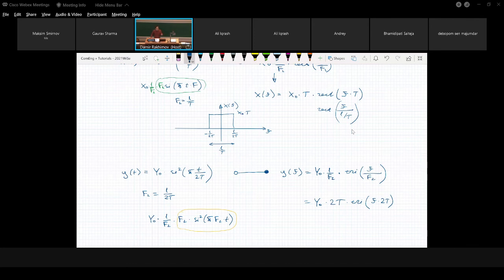This is the idea, that using a fixed carrier frequency oscillator and additional signal processing, you can decide at which frequency you transmit your signal. So I hope it's clear. But if it's not, please ask questions.